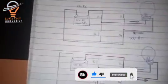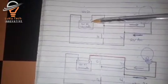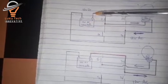So let's see here. If we switch on switch 1 and switch 4 and we power it with a 12 volt DC battery, the positive voltage will come here like this. It will pass through switch 1, because switch 2 is open, so it can't pass there. It will go to the bulb and then come back through switch 4.